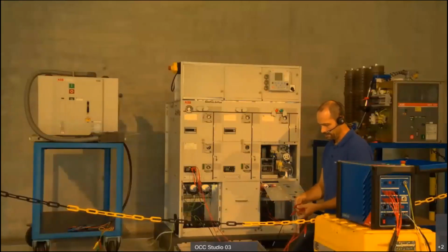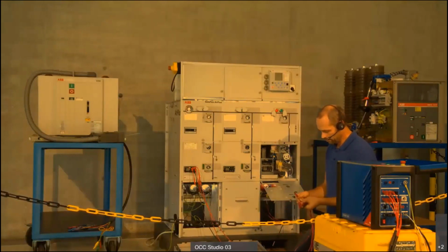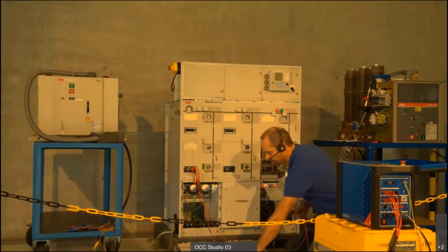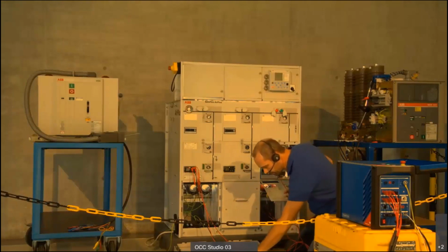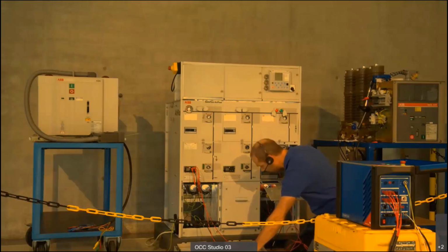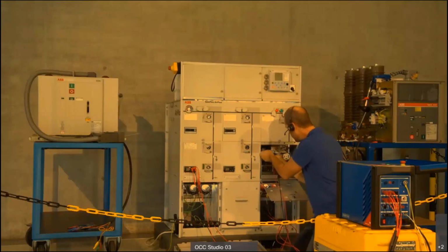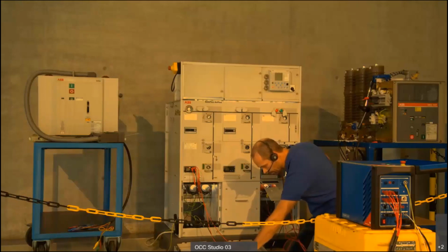So I take the B-row cable here. Using for the trip command B1, checking the schematics. Trip signal is X152. So we have 52. And the neutral BN goes to 52, sorry, 55 is the trip signal. Yeah, I put it the right way. So this one goes to the common. Okay, so the trigger is connected. Check again. Common is on 52, and on 55 is the trip signal.